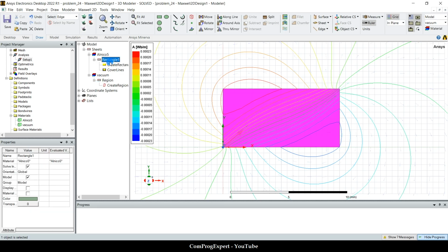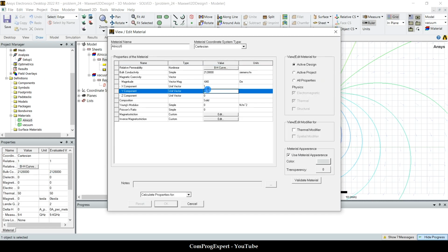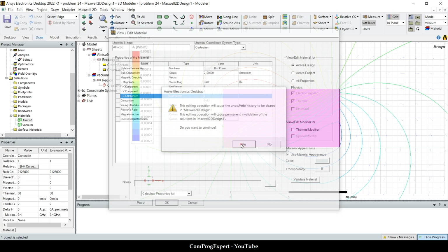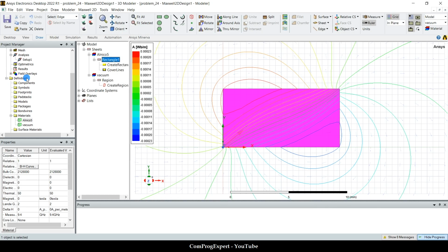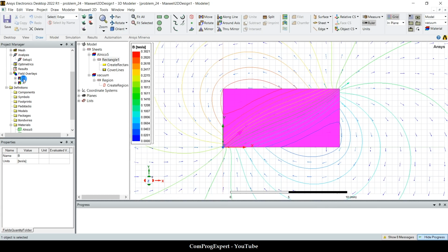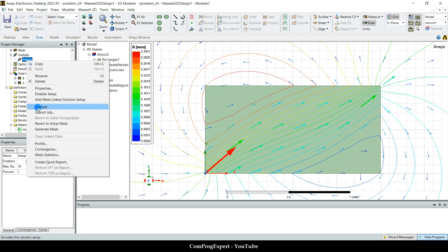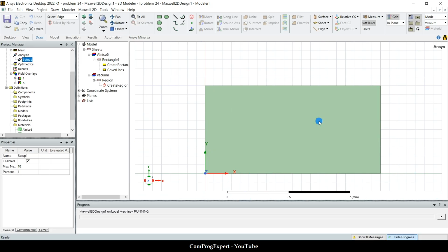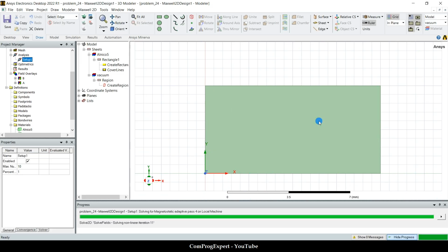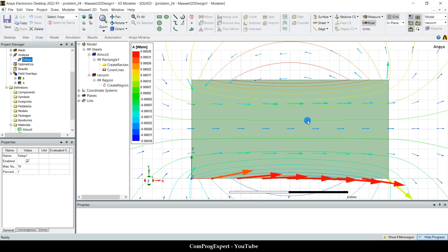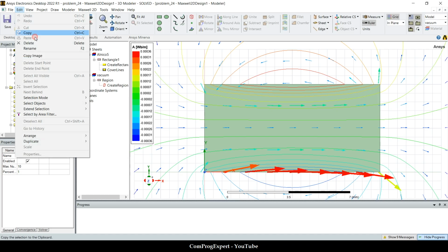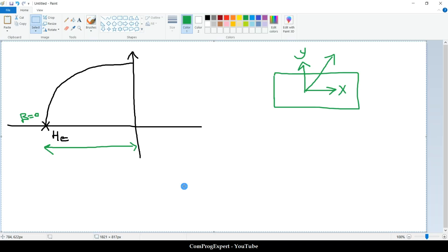So now let's plot the magnetic field intensity vectors. Here, let's set the direction of the magnetization in the X direction and delete the B. You can follow the B vectors. Let me rerun the simulation. I just want to explain this important concept that we have. These are flux density vectors of B. So you can see this pattern.